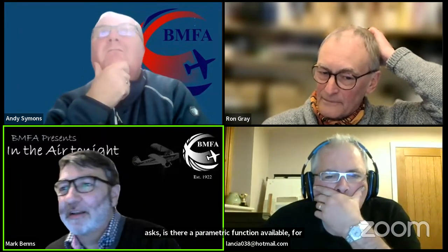Right. George asks, is there a parametric function available? For example, can you change a dimension and the sketch updates to that? We've just covered that, but certainly spars 5x5, for example. Yeah, constraints. Similar to what I did with the positioning of my spars, I had the dimension, and I said, right, change the dimension, and it changed the position.